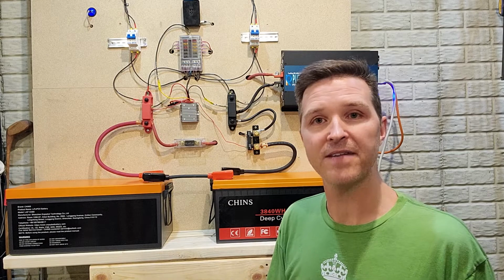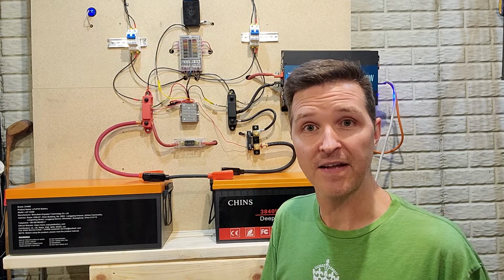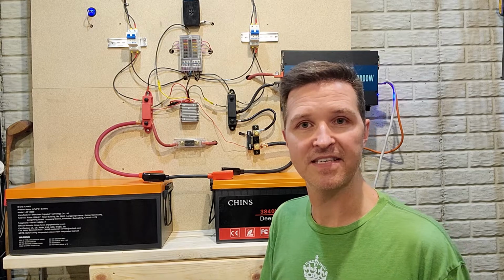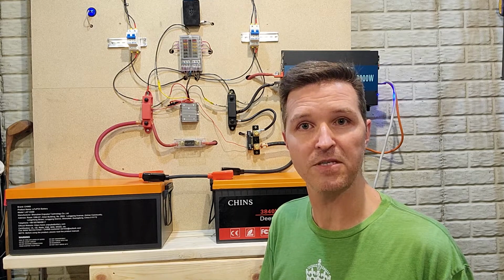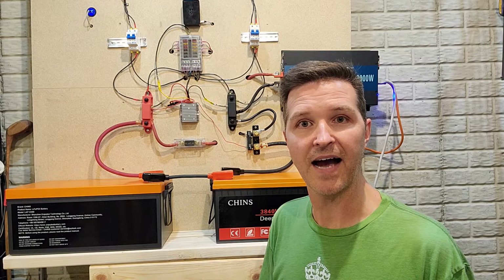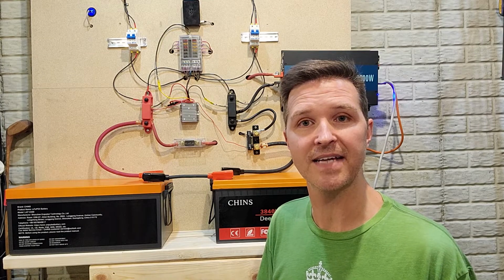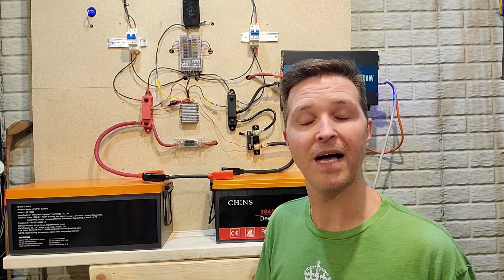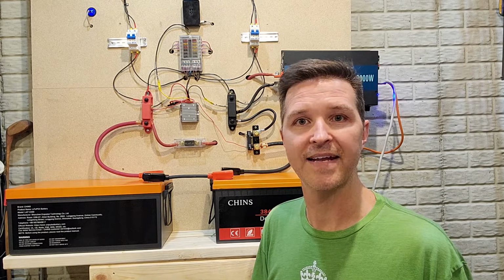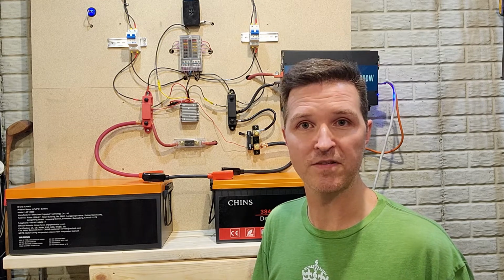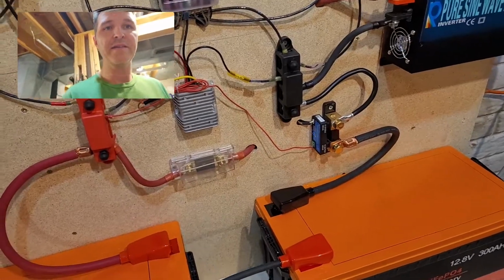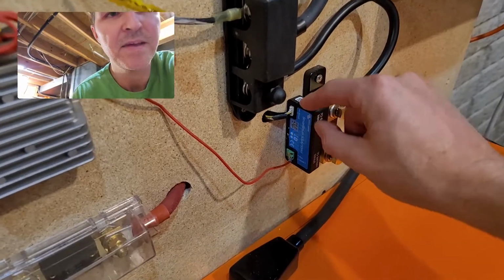And actually what I found out is my shunt can be hooked up to tell me that. What I have is a Victron 500 amp Smart Shunt, and I did not realize it, but you can connect a secondary auxiliary cable to the positive of one of the batteries, and it will tell you the midpoint voltage deviation of the batteries. Here is my shunt right here.